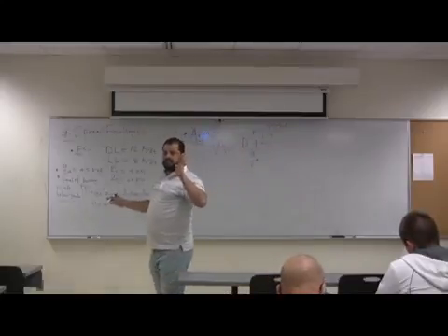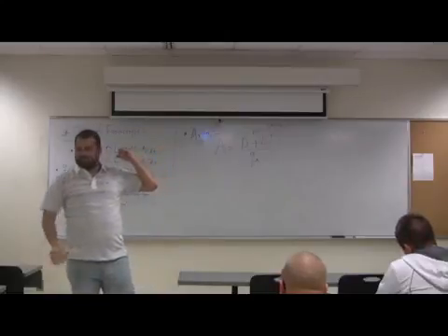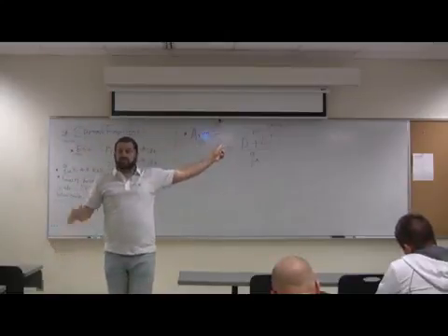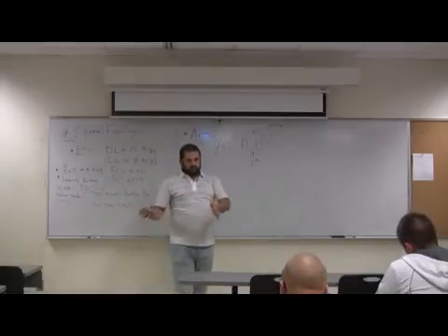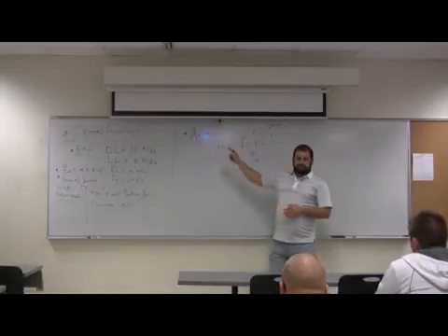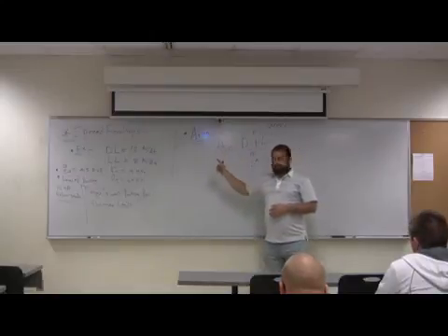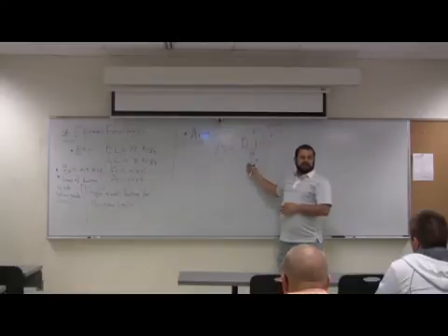Why? Because there is a huge factor of safety included in Q allowable. You don't have to magnify the loads for the area only, the area. I'm not talking about the depth or the reinforcement. So the area of the footing is calculated from the service loads, D plus L over that one.